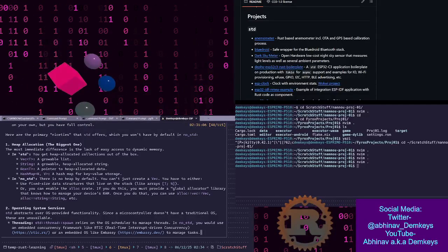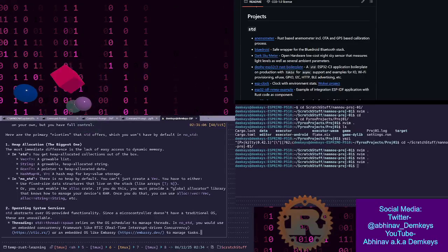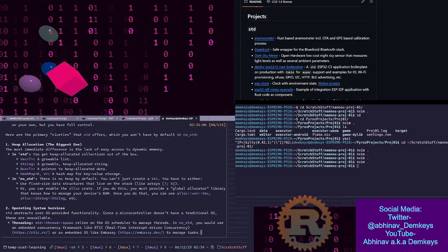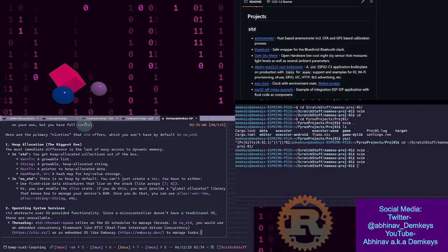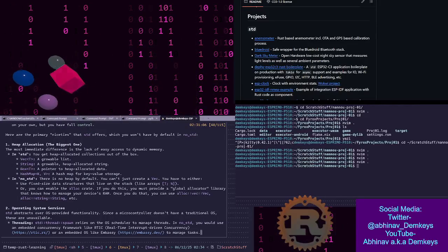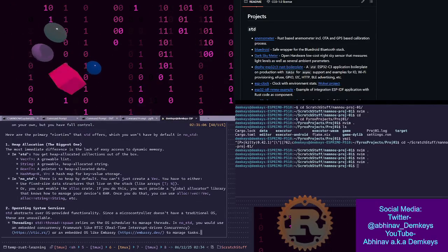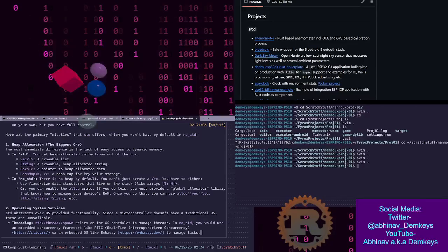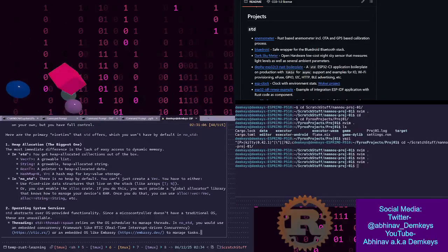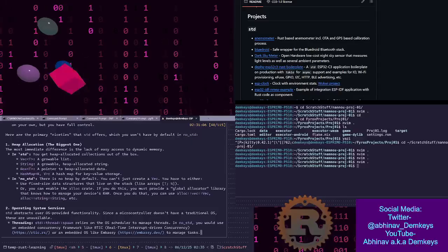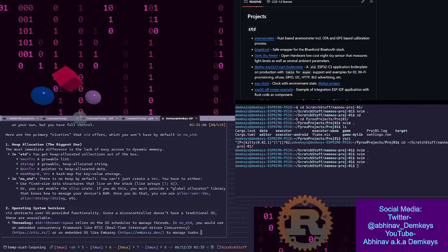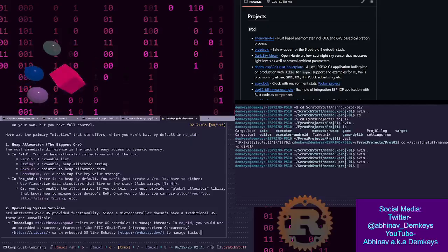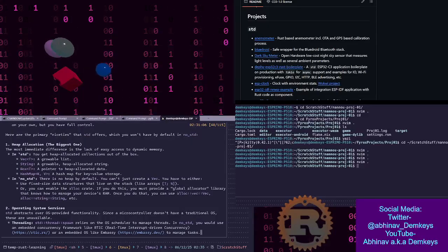Though there might also be situations where you're borrowing a variable, just so you're not unnecessarily making a copy of it. And you definitely want to avoid making unnecessary allocations, especially on limited resource hardware like the ESP32. On the ESP32, we are talking about KBs, maybe MBs of RAM.